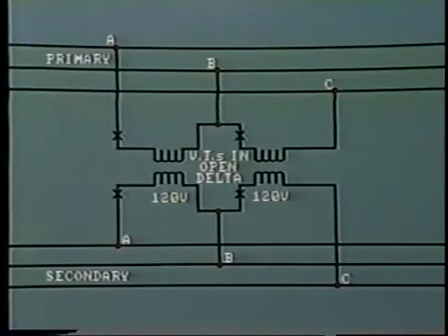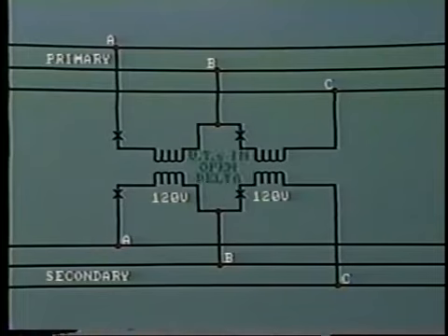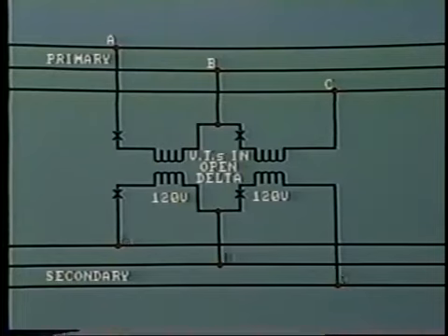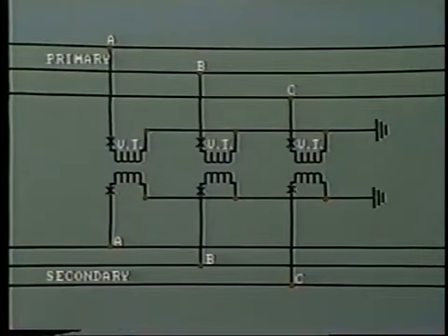Many protection relays require line-to-line voltage as an input. For this case, 2 VTs are used, connected like this. This actually provides an open delta arrangement on the secondary, and thus we have all 3 line-to-line voltages. Where line-to-neutral voltage is required, such as in generator protection, 3 VTs are normally used, connected like this.